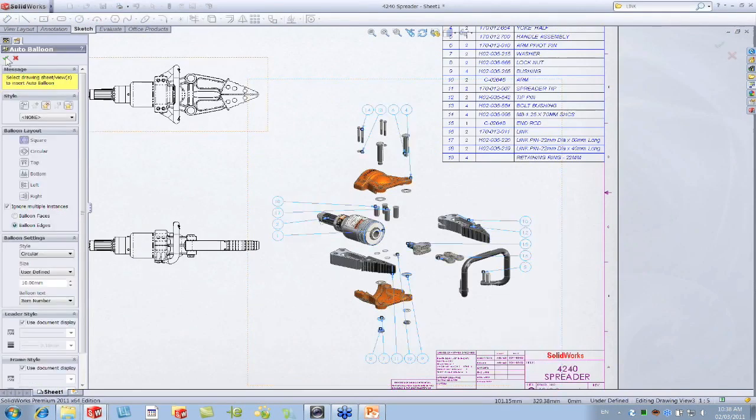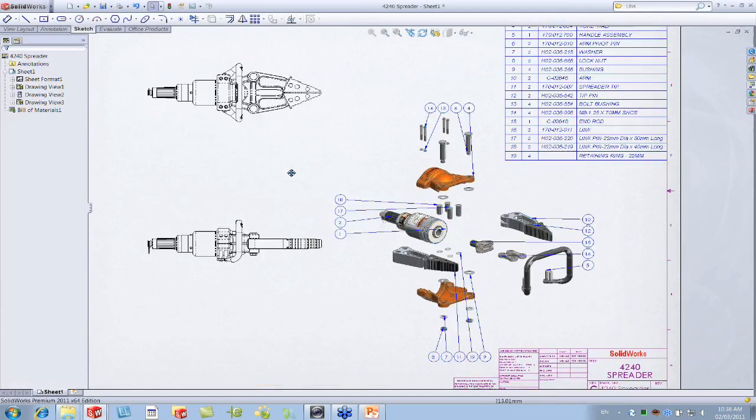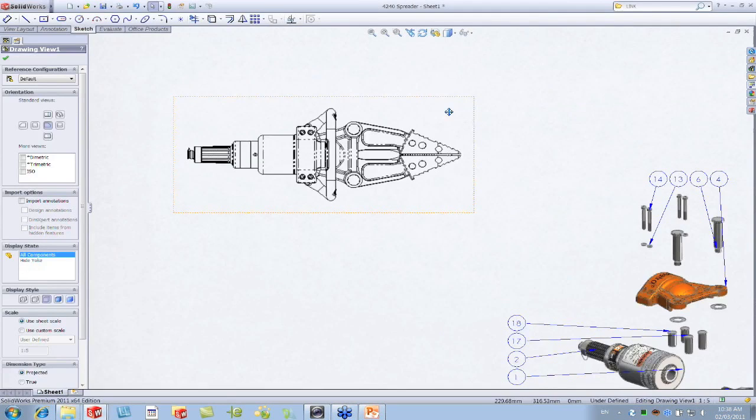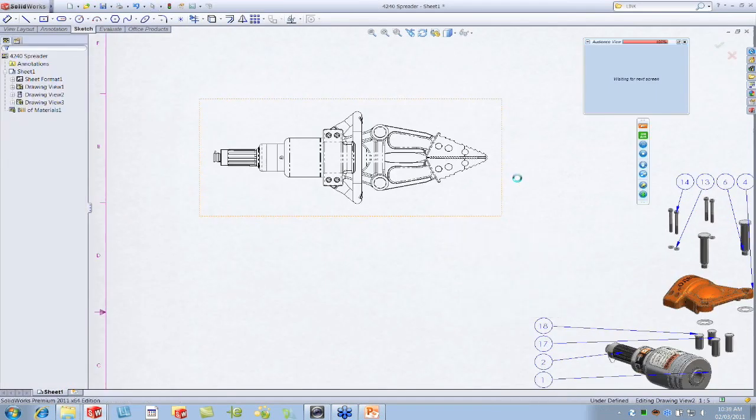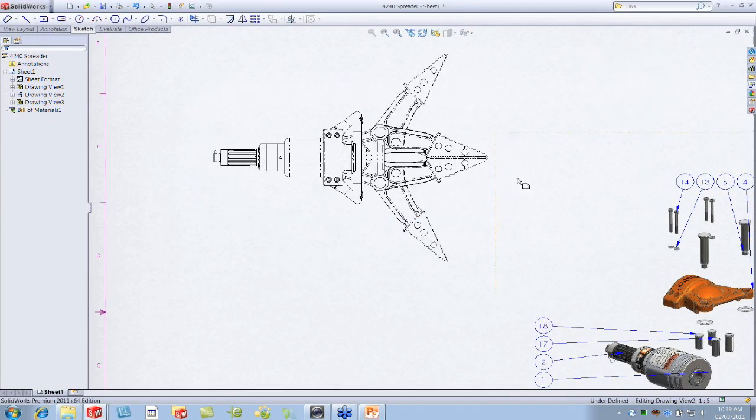Other thing I want to do in this drawing before we leave for something else is to show this jaws of life in the open position. And we can do that right within here too. So I'm going to say I want to create an alternate position. So I want to show this open and close. And what's nice by doing this showing open and close option here is that you can also dimension to anything.